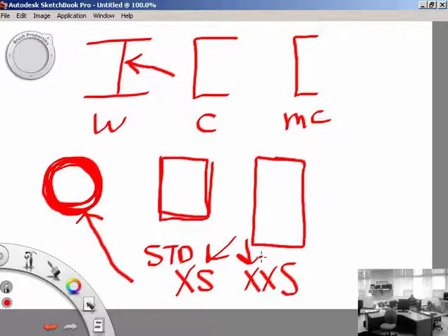Now, here's your next question. If I'm buying a 6-inch steel pipe, but I order extra wall thickness, where's the 6 inches? Is it on the inside diameter? Is it on the outside diameter? Any ideas? There's always an easy way to tell. You can Google it. I'll let you go figure it out. But keep in mind, and this is where people go wrong a lot of times, they make mistakes on whether they're dealing with ID or OD. You do have to know that.